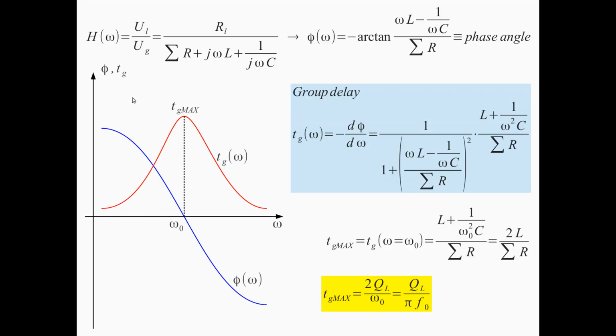So the group delay is also a quantity that's going to affect my filters. The group delay is frequency dependent. So it goes to very low values outside the passband of my filter, but it's very high inside the passband of my filter, and may distort my signals. It may cause intersymbol interference. So group delay is yet another problem we have. The differential group delay is a problem. If the group delay was flat, that was fine. It would not disturb the signal, it would just delay signals. But if the group delay is a function of frequency, then it distorts my signals.